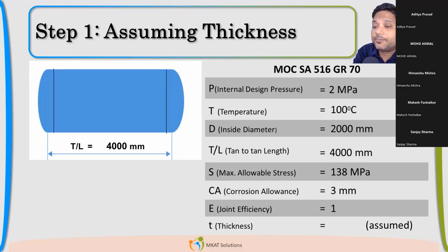Like after the plant is shut down and we take that vessel for maintenance. Before maintenance, we do steam out. In that steam out condition, which may be at a completely different temperature, a vacuum may be created because of the steam operation.